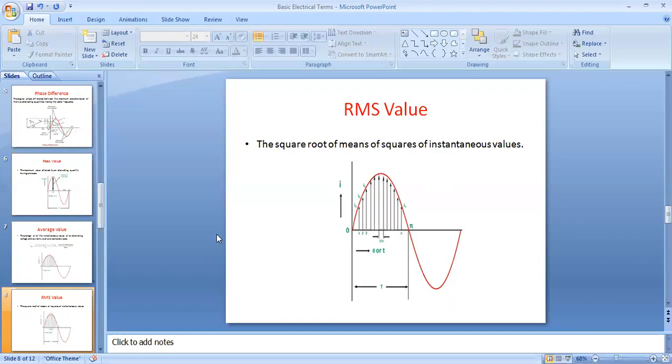So consider I is the alternating current flowing through a resistor R for time t seconds, which produces the same amount of heat as produced by direct current, that is DC. The base of one alternation is divided into n number of equal parts so that each interval is of t upon n seconds.